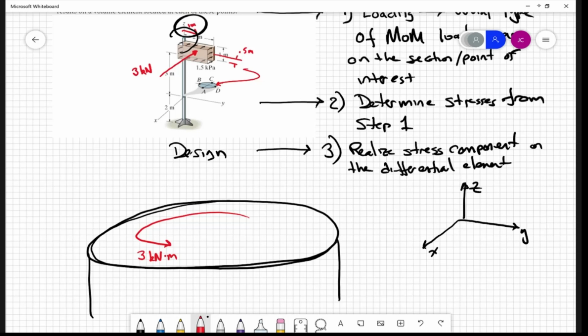All right. We got two choices for bending: around the y-axis, around the x-axis. Do we have either of those or both of those or neither of those? Only bending across the Y. Yeah, you got a bending about the y-axis, right? It's going to tend to make this thing topple over in that direction. So what's the moment arm that the 3 kilonewton force is going to act on? 3.5 meters. Right. It's the 3.5 meter moment arm, and that's going to act around the y-axis.